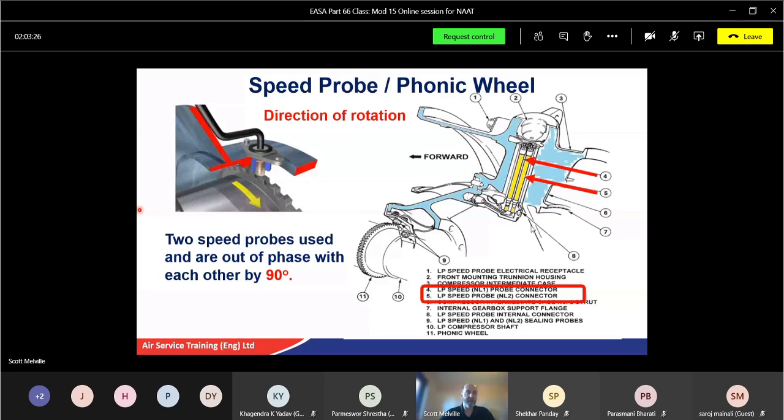So ideally, if you're going to start an engine on the ground as an engineer and you see the engine going the wrong way, what we used to do is an old trick. We get a big bin lid and put it at the back of the exhaust so the air could not flow through it. That would slow the engine down, and once it stopped, then we go for an engine start. But the best thing is obviously when you go for an engine start on the ground, where possible, always have the aircraft heading into the wind. If it's heading into the wind, then it will rotate the right direction. But again, if it's a really windy day, it could be too fast. Even though it's going the right direction, that might be too fast. So you have to be very careful.